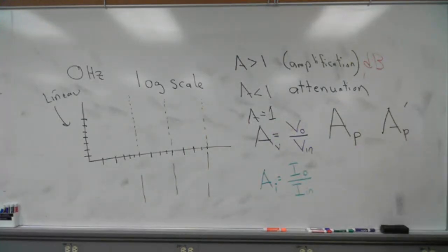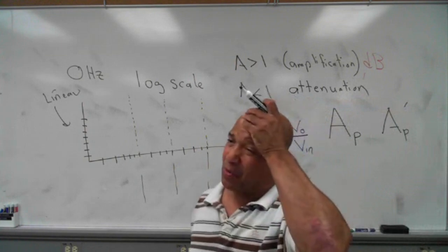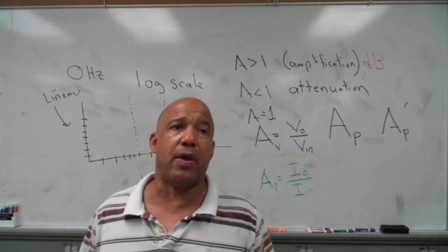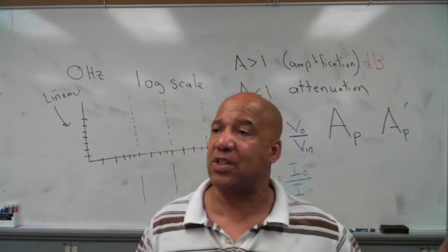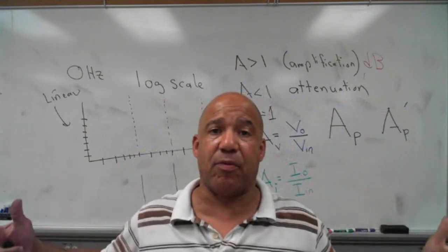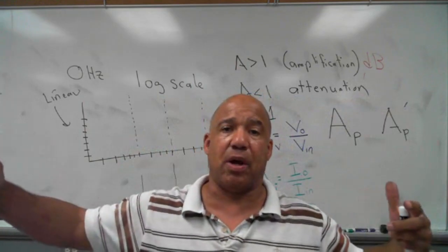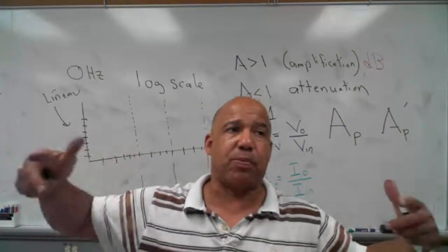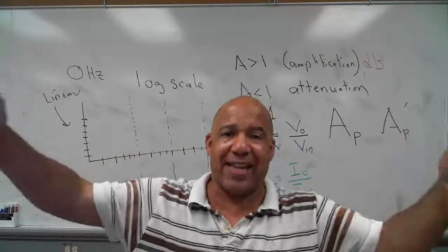And you can just imagine the dB there. So this is the dB gain, and this is the power gain. Now, you might wonder why would you want to show it both ways? Well, if you remember that a logarithm is basically an exponent. And remember what happens when you multiply bases, you add the exponents.